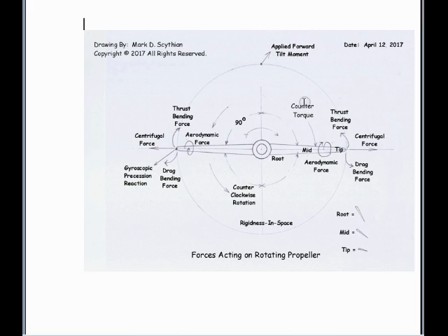Next, the counter torque. If this was an airplane, you would have much longer wings outward, which make it hard for the counter torque to really cause the airplane to roll to the left. But even if it did, even if you had a much longer propeller, you also have control on the ailerons to turn the yoke a little bit to the right to cancel that torque out.